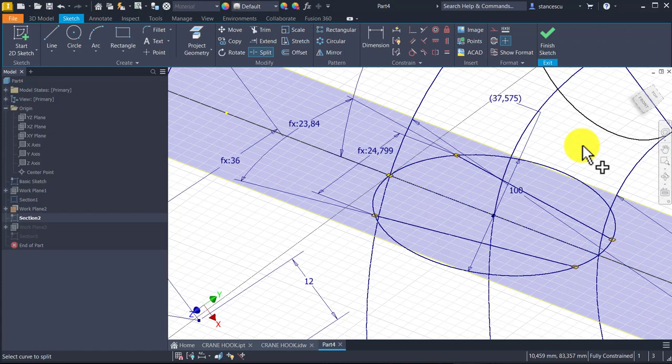It remains a circle if I cut at 1 point, because 1 point has no dimension. This is why when you select the first arc, you receive 2 points of intersection. Good. I select this arc and this arc, shift to select the second one, and I apply